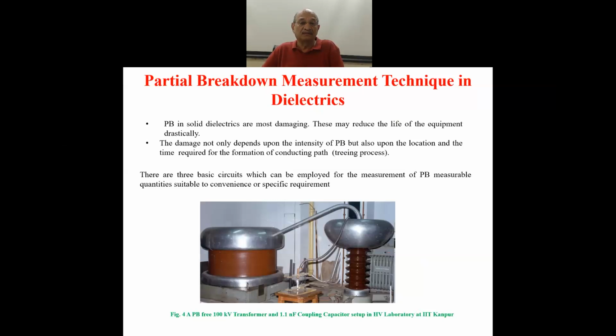So partial breakdown measurement in gaseous as well as in liquid dielectrics is also done, but it is not that damaging as in the case of solid dielectrics. The partial breakdown in solid dielectrics is most damaging, as you read in the first line of this slide, and it may reduce the life of the equipment drastically.